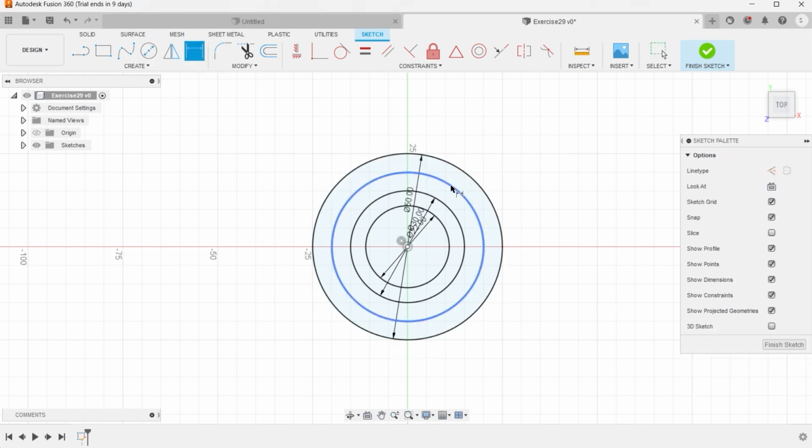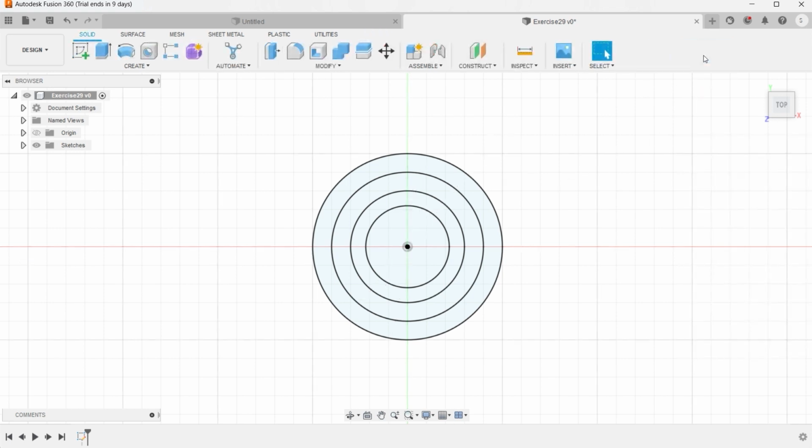This is not defined, so we can put diameter of this one as 40 mm. You can see all the sketches are having black color. That means the dimensions are fully defined. So we can finish the sketch, and that can be extruded to different depths, right? Fine. So we need to start extrusion or press pull. As a shortcut, we can hit Q, and it can be initiated.